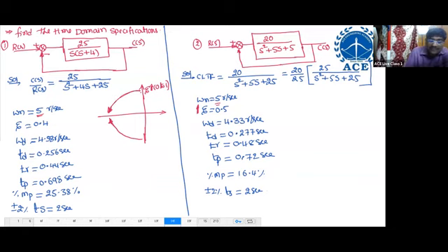In this case, the poles are moving left, which means the time constant decreases. Next, settling time decreases. The imaginary part is decreasing, so omega d decreases. Omega d decreases means TR, TD, TP all increase. Next, zeta increases means the poles are moving left near to the real axis, so percentage of MP is going to decrease. Check it one by one.